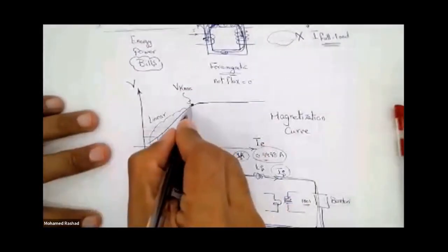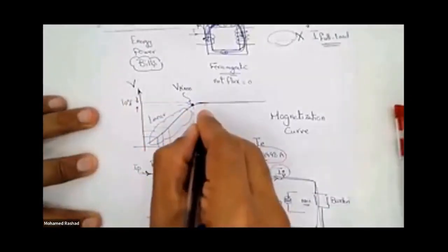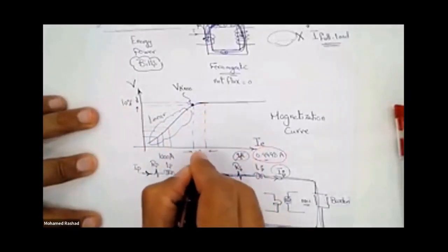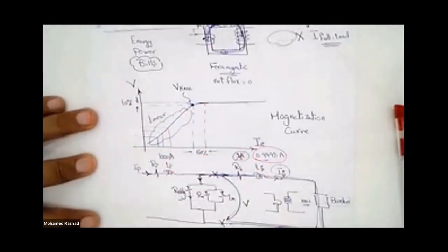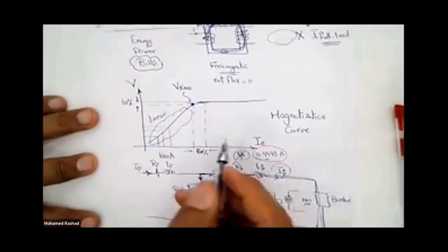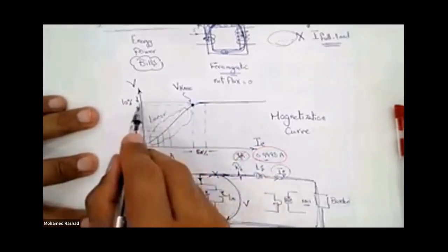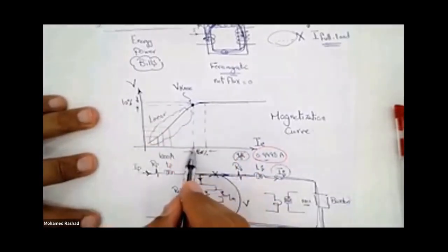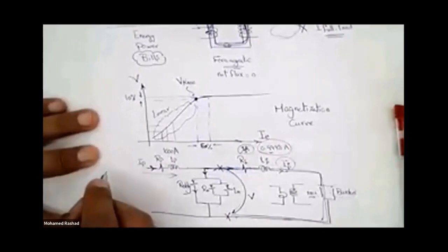We found that as you increase the secondary current, the voltage appearing on the secondary increases by 10%, but the magnetization current increases by 50%. This means that this is the point after which the voltage does not increase more than this. And the magnetization current increases, meaning that as more current passes through the primary, the losses increase significantly, while no current goes to the secondary. What does it mean that no current goes to the secondary?